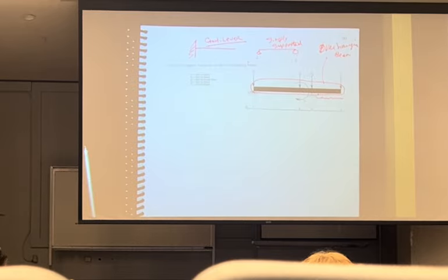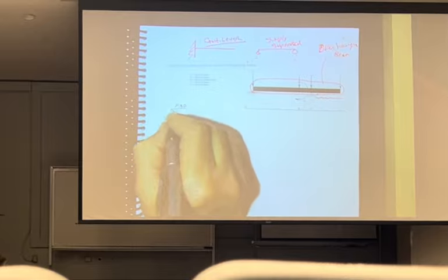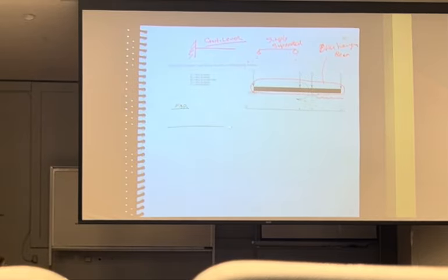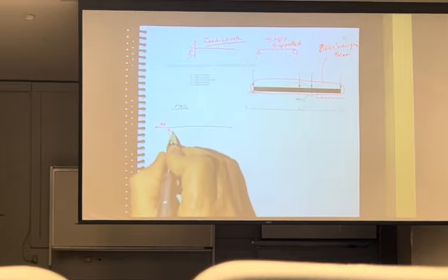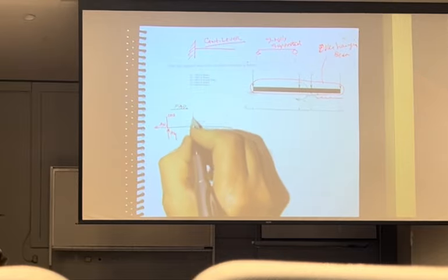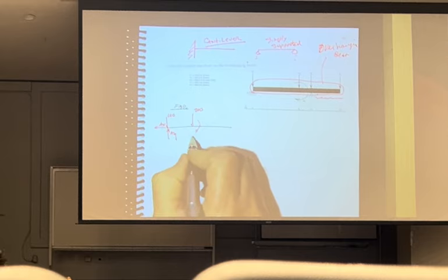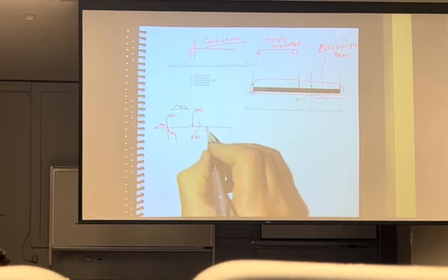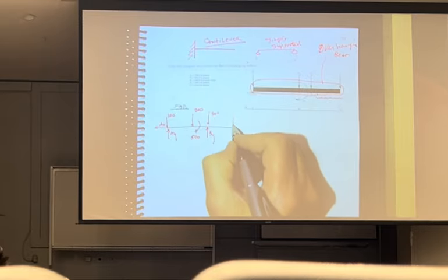All right, so my free body diagram of this is easy. Beams are the easiest. What do I have? I have an AX, an AY, I have 100, I have 200, I have a moment of 500, I have a BY from the roller, I have 300 applied load, and at the very end I have 400.